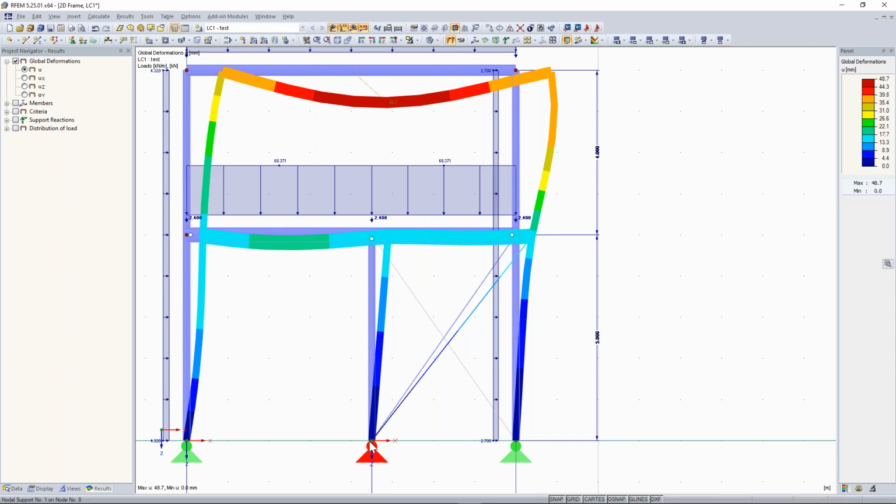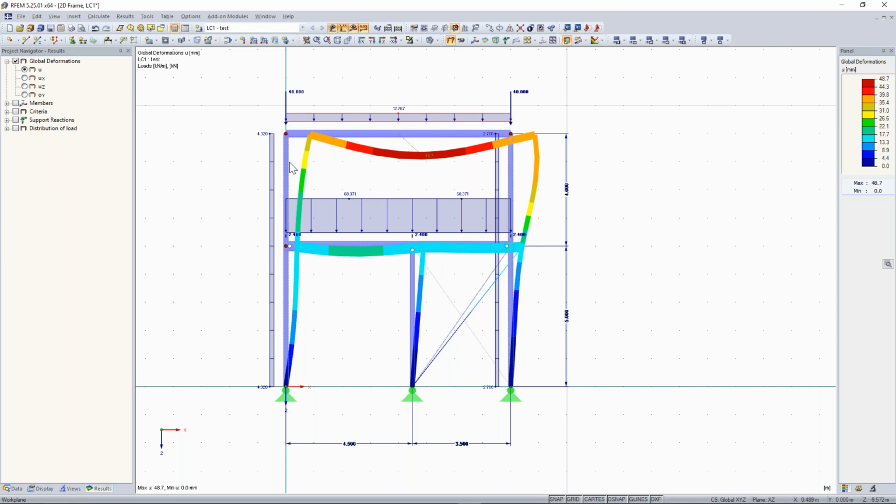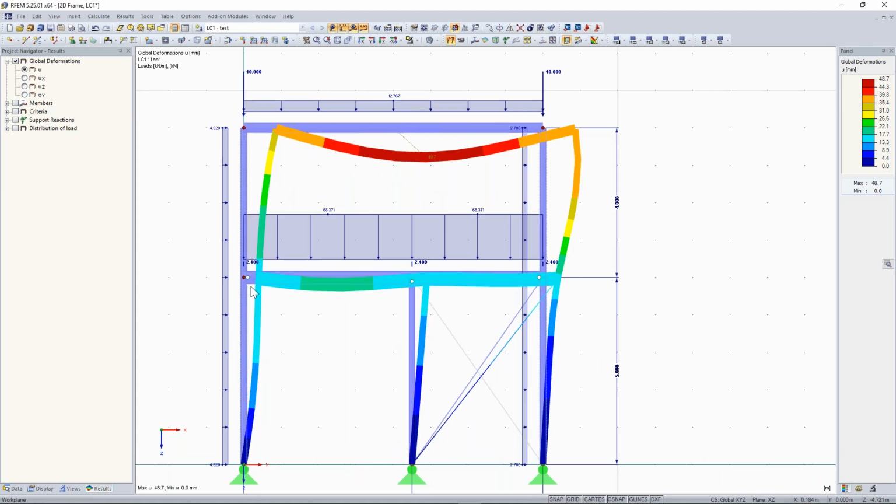It got a little bit longer. So here we will get tension forces and do also some plausibility checks. So can it be possible? We have here this horizontal load, also this vertical load. So is the deformation correct? I would say yes, it is. Also here, it is supported by these columns, this beam here. So I think it's pretty correct.